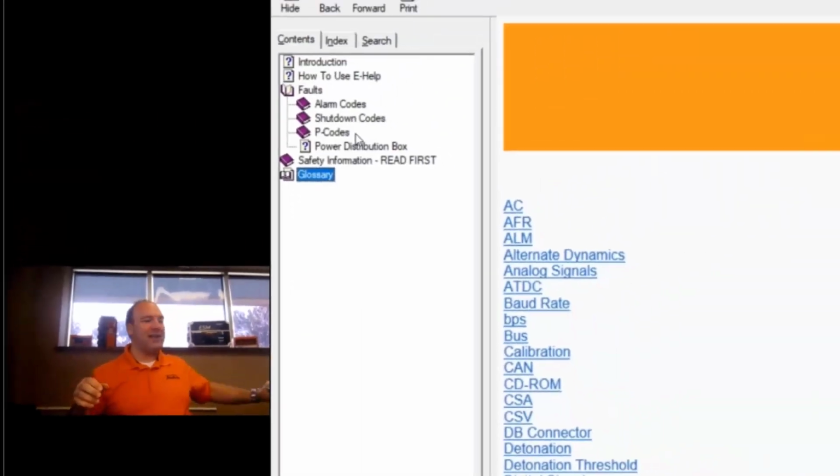So if you see one of these silver boxes, there's going to be another HMI, whether it's a 5-button or an 8-button. Out of this module, it has its own fault codes, whether that's for a stepper or an emission system. But we didn't want the numbers to be the same as what came out of the ECU, because these codes can't be sent back to the ECU. They live within this box. So we created P codes that you would access through that HMI in order to troubleshoot the components that are connected there.